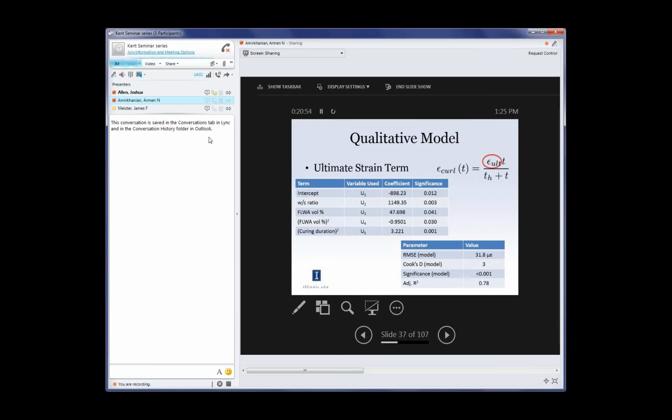That's not as good. So we already saw from when we did this analysis that we wouldn't be able to actually predict accurate numbers, but we could predict accurate trends, which is really what we were after, because this is only one type of mix design using limestone aggregate. So obviously when you change aggregates, you're going to have slightly different behavior. So we didn't want to predict design values. We want to predict design trends.